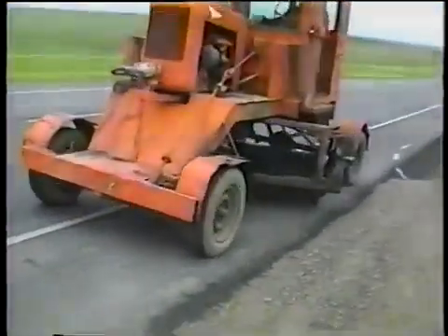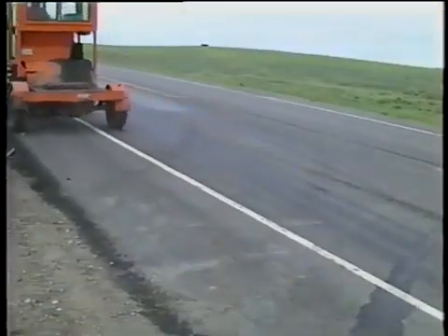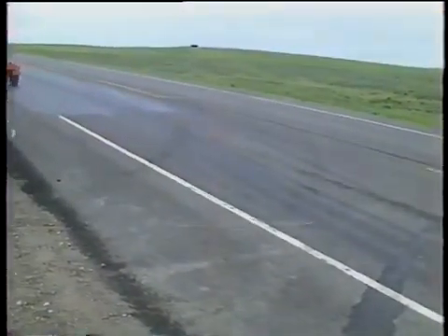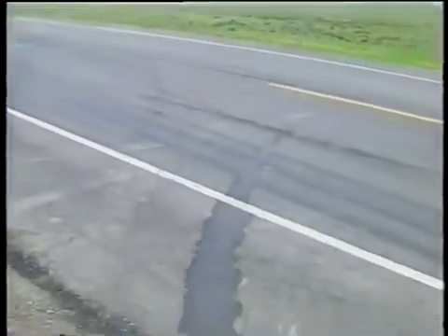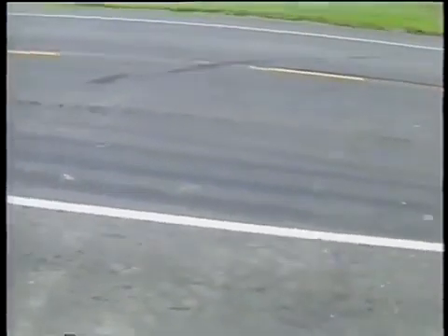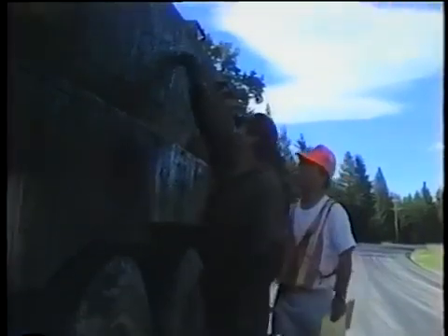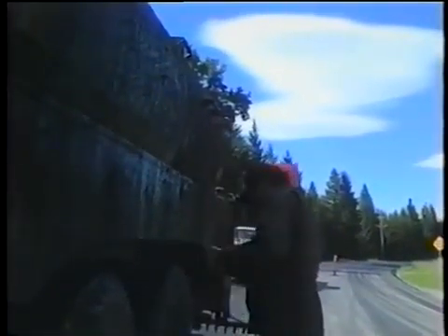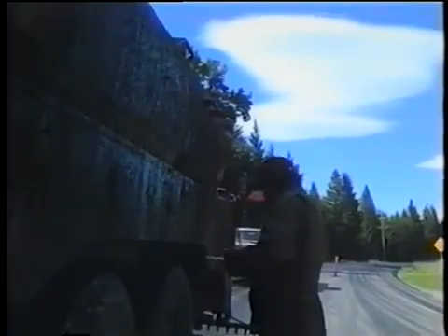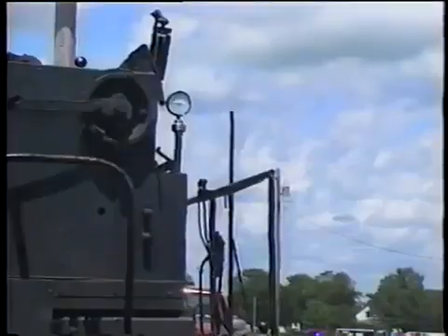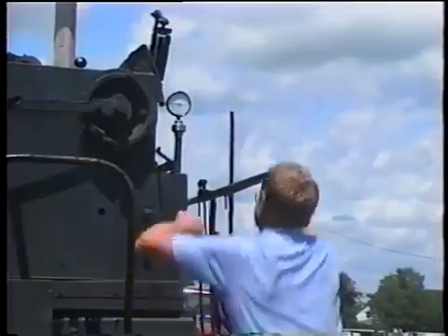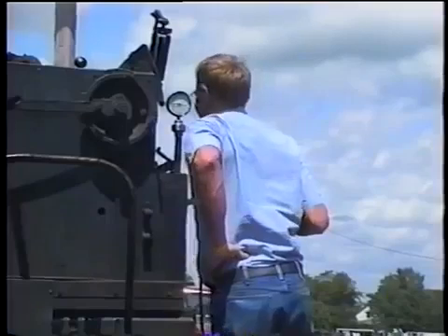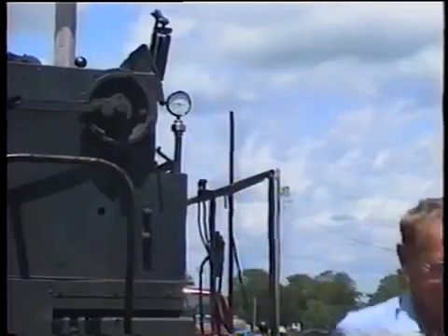Before the material is applied, see that the surface is both clean and dry. Otherwise, the tack won't bond the new pavement to the existing surface. Then, verify that the tack material has been heated to the proper temperature. The contract documents typically give a temperature range. Also be sure that the distributor's pump pressure is correct and constant according to the manufacturer.